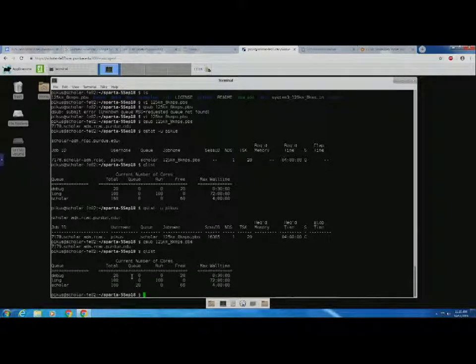I saw that you were coarsening and refining your grid based on number of particles. Is there a number where we can be confident that our results aren't being affected by how we're refining our grid? The reason I like to go by number of particles is that there's a rule of thumb in DSMC. If you want at least 20 particles per cell, that's actually more strict.